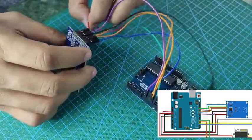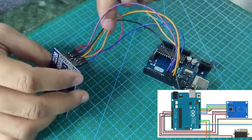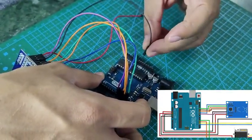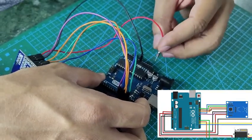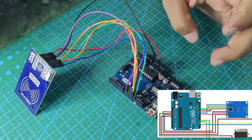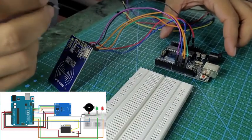Now let's take the red jumper cable, that is the positive connection, and the black cable, that is the ground connection. So put this black cable on one of the ground pins on the Arduino board. Now this red pin is connected to 3.3 volt, not on 5 volt. So 3.3 volt pin on the Arduino. So this is done. Now let's connect LEDs, buzzer and servo motor to our circuit.